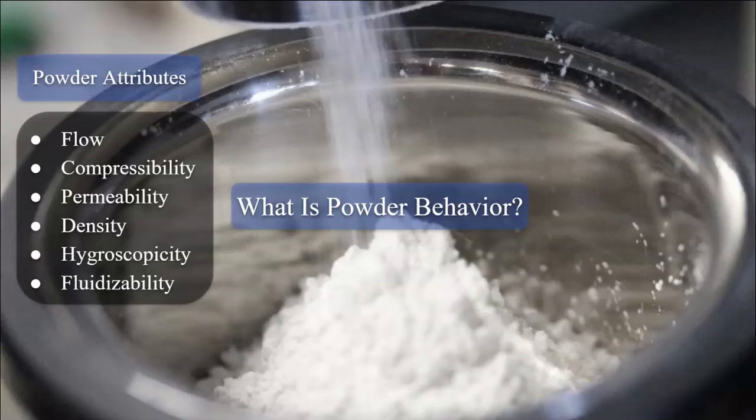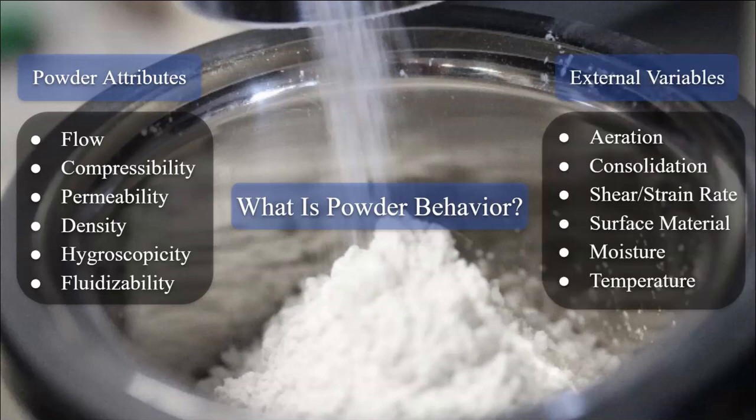Well, what is powder behavior? Well, this is going to be the accumulation of these powder attributes, going from flow to compressibility, all the way down to density, and we're going to talk about what those mean in just a little bit. And something that we can look at are these external variables, which can actually affect how powder behavior occurs. And these can be things like aeration, consolidation, and surface material. And so we're going to explore what those mean.